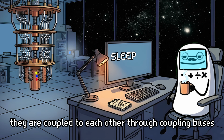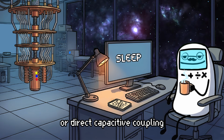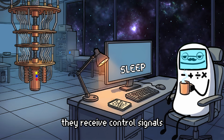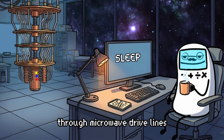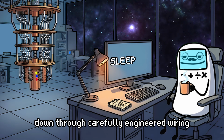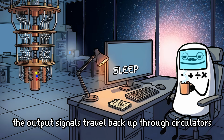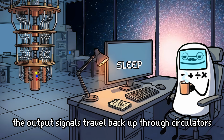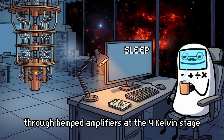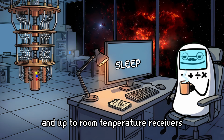They are coupled to each other through coupling buses or direct capacitive coupling that enables 2-qubit gate operations. They receive control signals through microwave drivelines that bring precisely shaped pulses from room temperature electronics down through carefully engineered wiring in the refrigerator. The output signals travel back up through circulators, through parametric amplifiers at the mixing chamber stage, through HEMT amplifiers at the 4 Kelvin stage, and up to room temperature receivers.